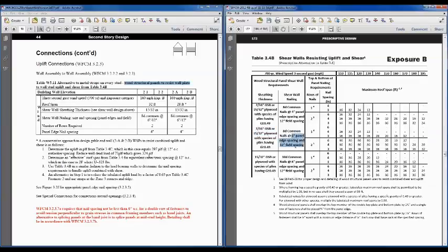We've got a 6 and 12 nail spacing, and so that shows up in this first row. And so if we were to reduce that nail spacing around the perimeter down to 4 inches and work out here to the 160 mile an hour column, we see that doesn't quite work. We can't really get that to work.